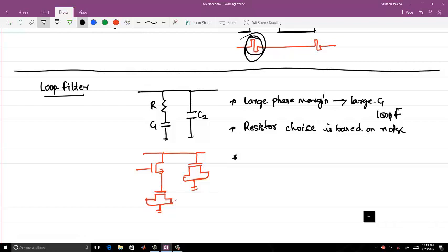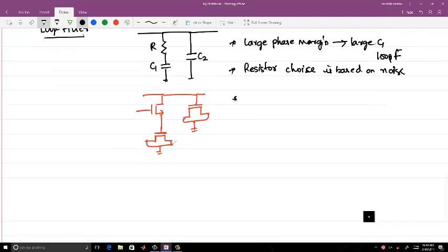So no, what you are saying is this. Are you saying that if I try to realize this capacitor with the MOS capacitor, the equivalent circuit will be some capacitor plus a resistor to ground? How many models and schematics have the substrate? Okay, so few will be there right now. I agree with you that all these capacitors will come with a resistance, but look at how much resistance, and at what frequencies are you working.